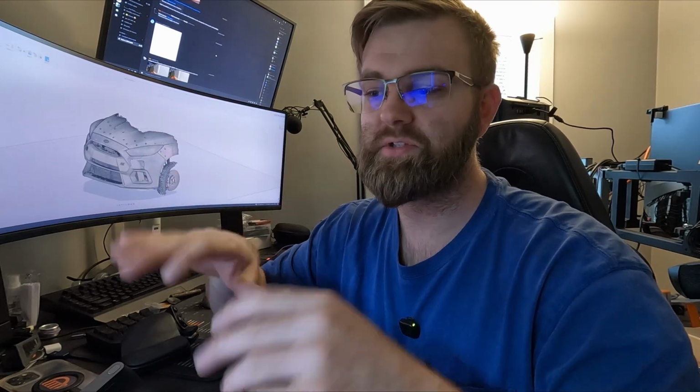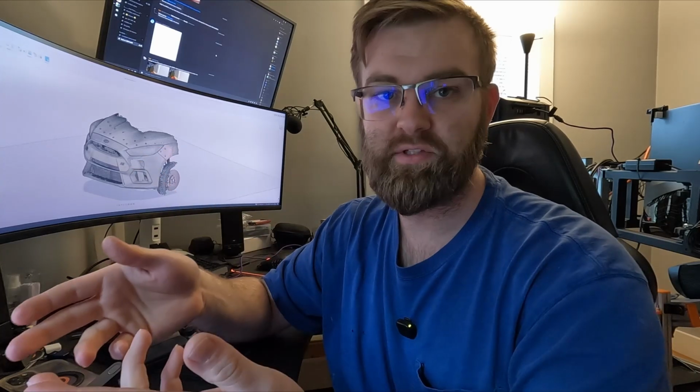Now, it is okay to get frustrated, and sometimes I redo that initial 3-2-1 alignment several times. It is not super intuitive, and sometimes if you're trying to use the intercooler like I did, you could be clicking on a divot inside the intercooler, so then your plane gets all skewed. So it's really important to have good, clean areas to do these sorts of alignments.